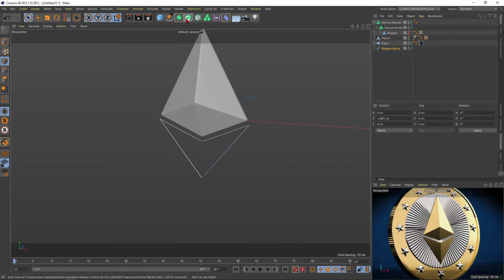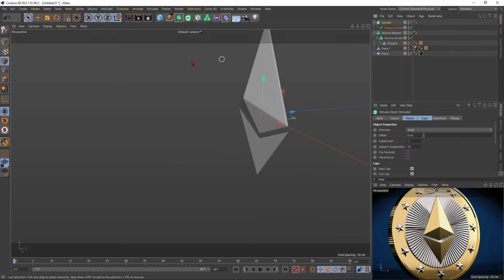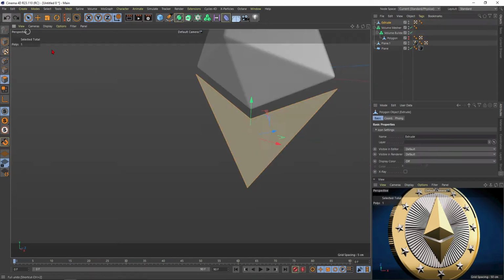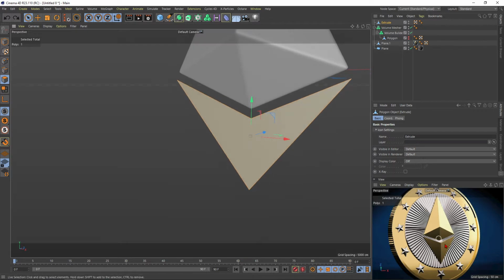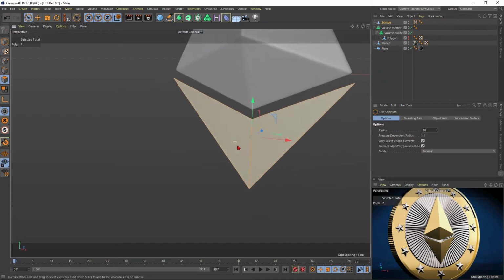Now I would say you just put this one into an extrude. All right, that looks nice. Just put this one to maybe 0. All right. Make it editable. All right. Get rid of all of this one. And now we have just one polygon here. We need to have this center line. So KK to connect from here to there. Spacebar to get out of the tool.